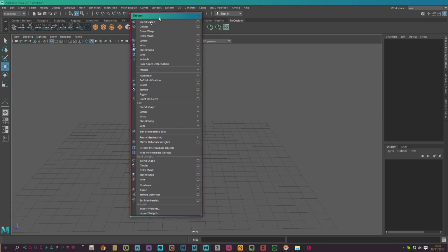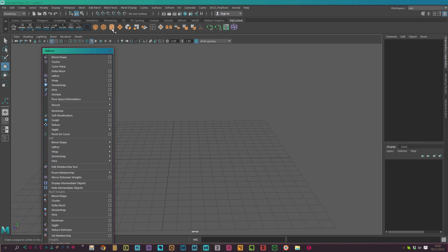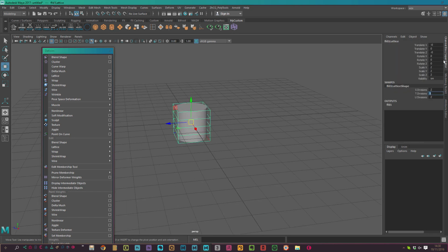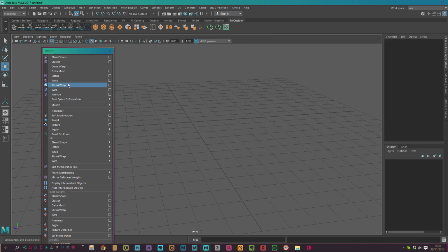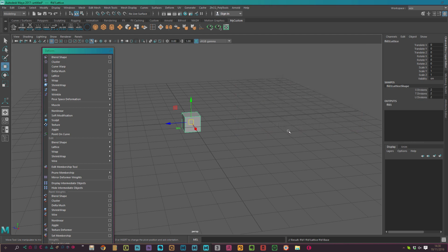And what's interesting? Yes, in deform, some nice deform tool like the lattice, of course, really important tool. Lattice, I think by default, I don't like the setting. I want a setting of 222. So I will customize that here. I will make a setting by default of 222. Just apply.